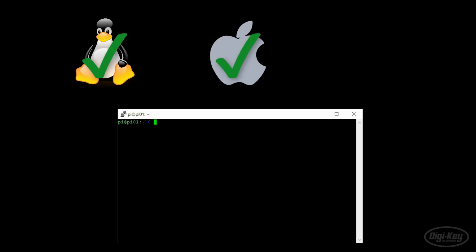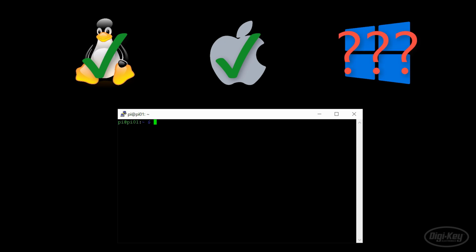The steps I'm about to show you should work for any build system, including make. You'll need to run a make file inside of TensorFlow, which will generate a template file structure. You then copy those files over to your project and include the necessary header and source files in your build system. To generate the TensorFlow Lite file structure, you need to use Linux or macOS. I have not gotten this part to work on Windows yet. If you're on Windows, feel free to dual boot or use a live USB distro of Linux.